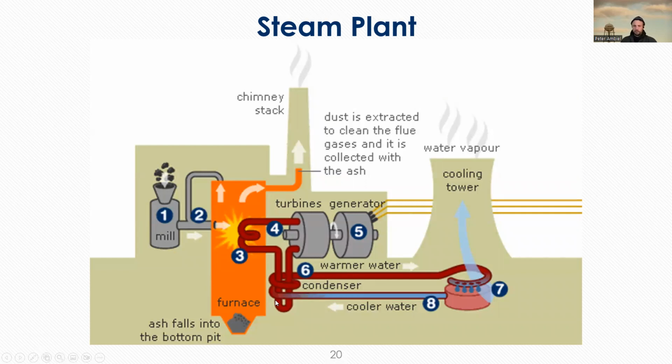So why would you do that? The reason for that is the water that you're putting into the turbine can then be a very pure stream of water without the possibility to introduce any contaminants. And this allows you to not have to purify and refine your stream of input water because you're using the same water over and over.